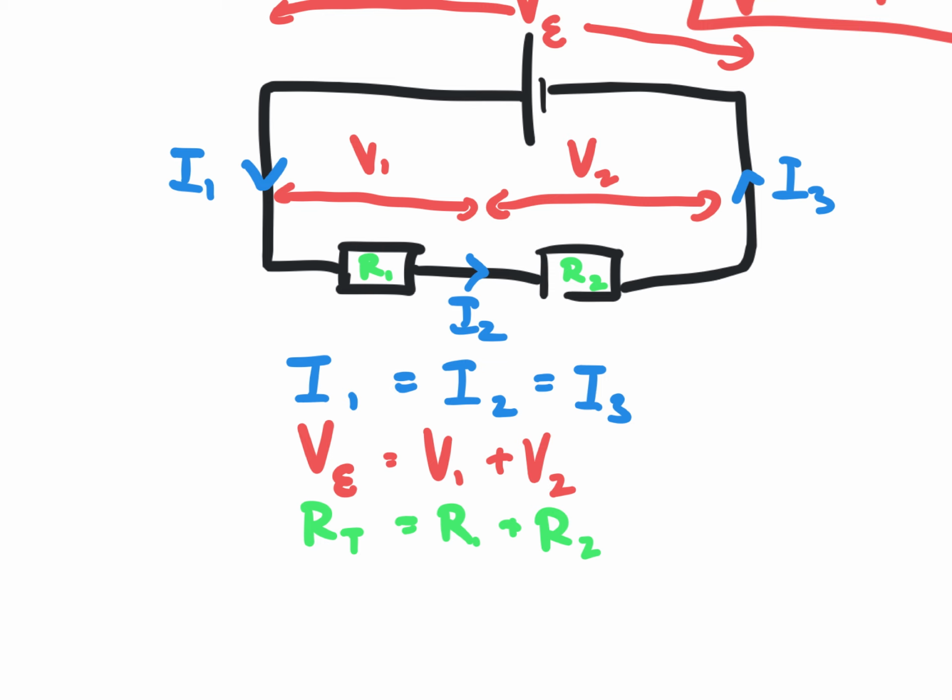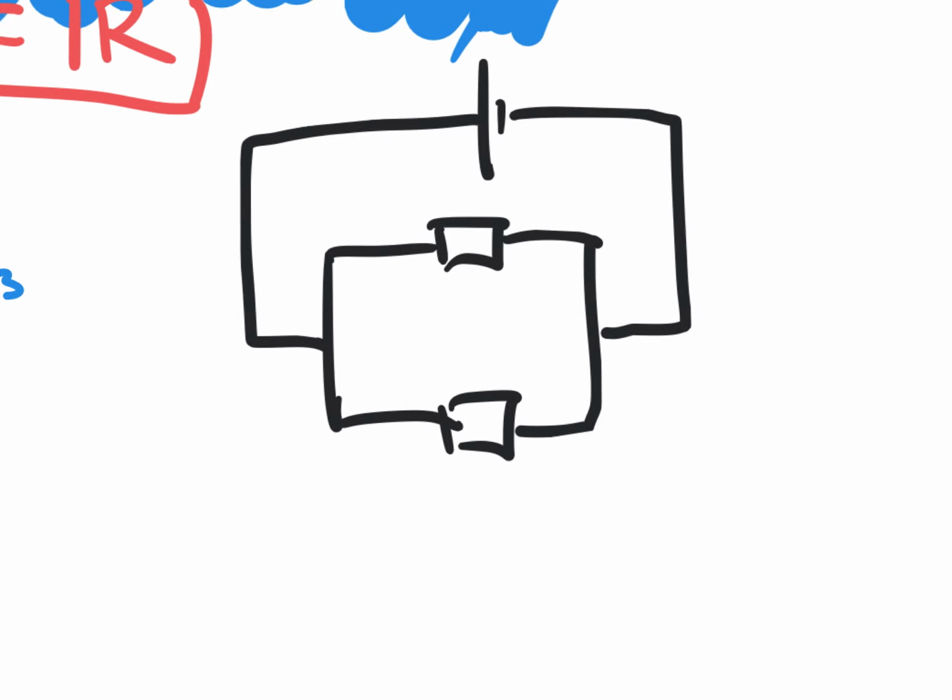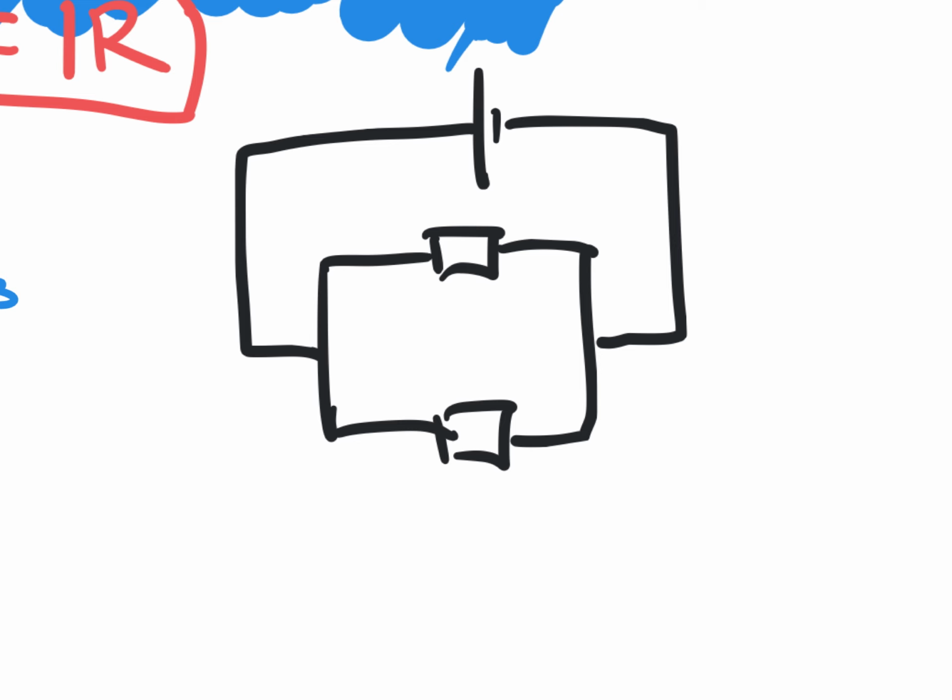This plus that. Easy. What about for my parallel arrangement? Parallel arrangement is going to be a bit different. Let's look at the current over here, I. Now, the current over here in the main path is going to split into two: I1 and I2.